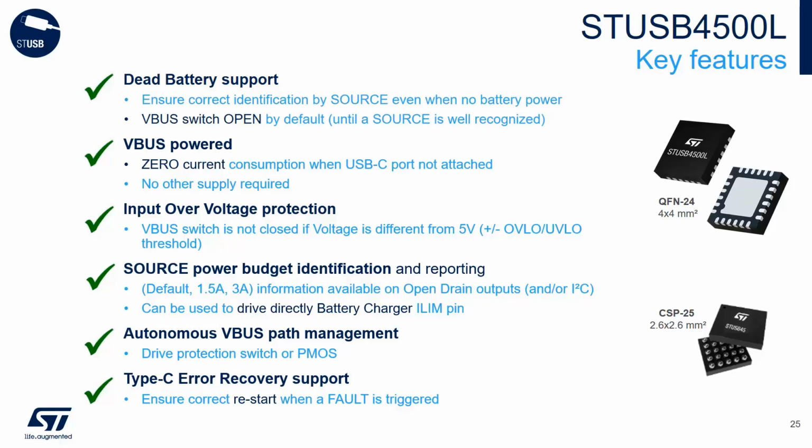The key point is that with a ST-USB 4500L design, the protection switch is open by default, meaning at the cable attach, and it's closed by the controller only when the electrical conditions are correct. In contrast, using a discrete implementation where a microcontroller must be powered up to negotiate the power contract, that means the protection switches are closed by default and opened only when a fault occurs. And it might close again outside of the USB-C negotiation, leading to interoperability issues.